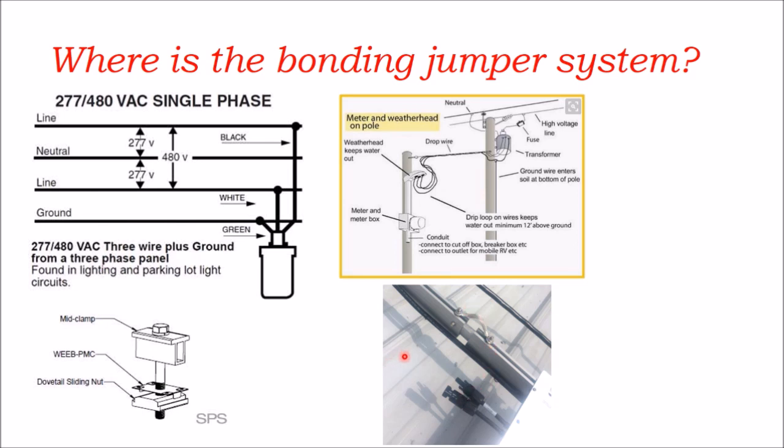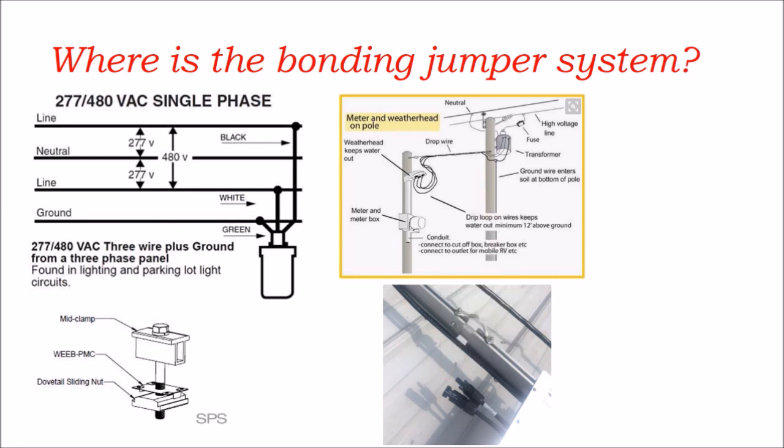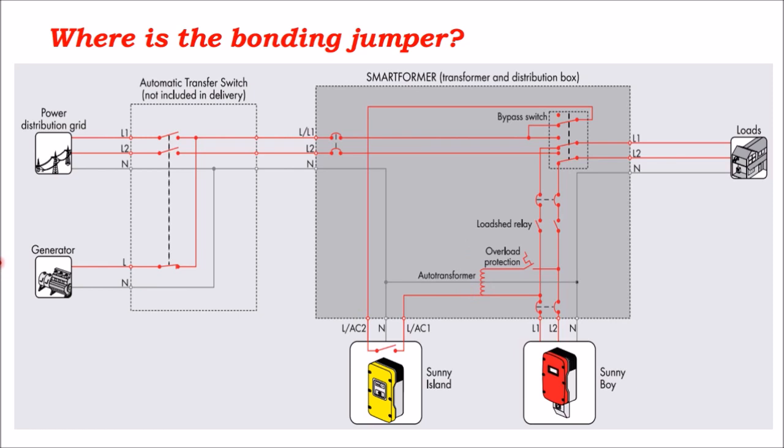Now, sometimes the metal roof can be used as an equipment ground conductor. I don't really like that concept so much because I'd rather control where the electricity goes than spread it out over a surface where who knows what could happen.